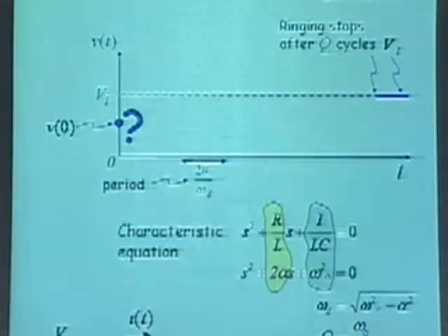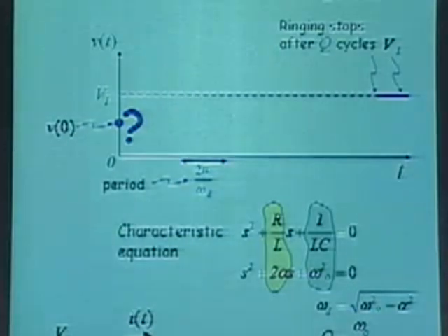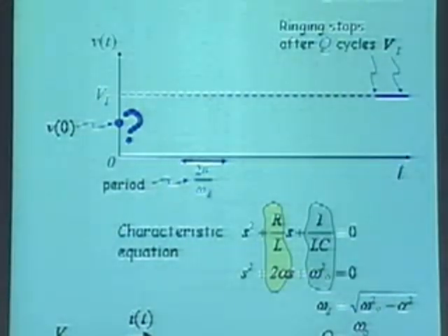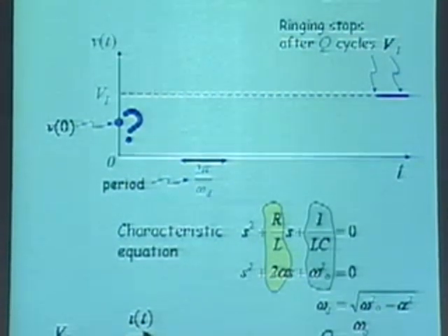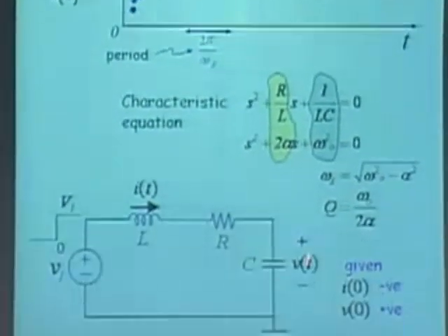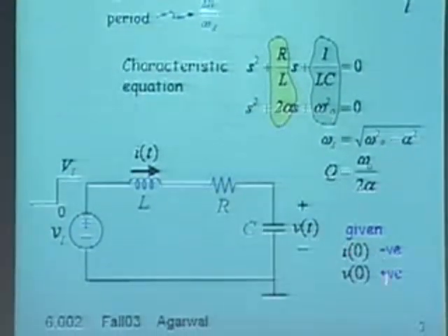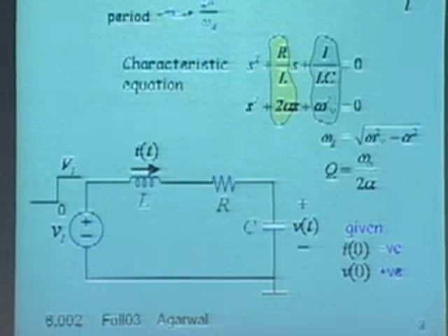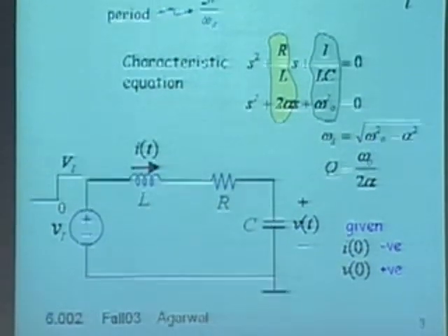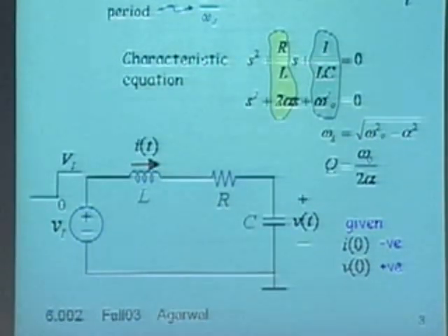Okay, and I start at this point in the last lecture, and I let you think about how you can stare at the circuit and intuitively figure out whether this goes down or that goes up. So here's the insight. Let's stare at this for a minute, purely through intuition. The capacitor has a voltage V across it, because I'm telling you that it has an initial voltage V. Now, I want to find out at time t equals 0 plus, in which direction does the capacitor voltage go, increase or decrease?